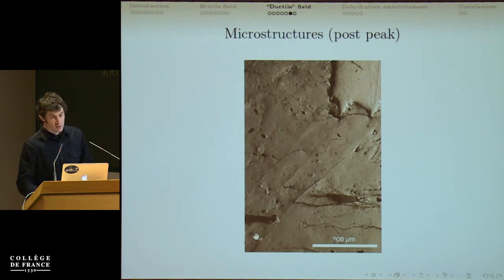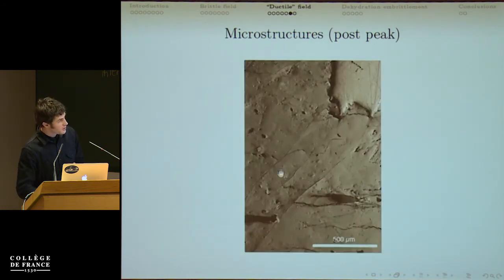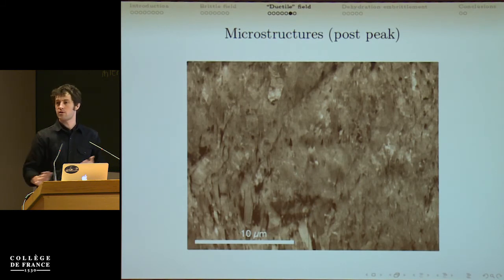Then if we zoom in on that, we don't have preliminary information, but this is what it looks like inside this kind of mush, a very, very small grain size. You see that you have some cracks. You have a grain size reduction that's completely ridiculous, so we can't see any grains at this scale. We tried to zoom in even further, but we couldn't get the high resolution with this SEM and Oxford. So essentially, what we have is extreme grain size reduction and no indication of dislocation creep or dislocation dynamics or diffusion at that scale in those experiments, even though we are at 1 GPa and 400 C.